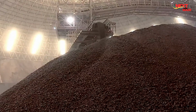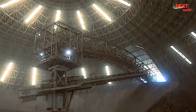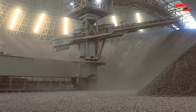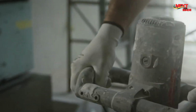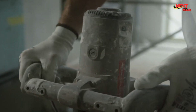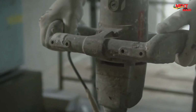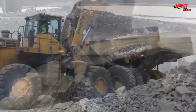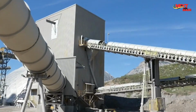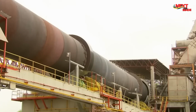The cooled clinker is then ground with gypsum and other additives such as fly ash, slag, or pozzolana in cement mills to produce a fine powder. Gypsum is added to control the setting time of the cement. Once prepared, the cement is ready for transport to the concrete factory. Because cement is such a crucial part of concrete, cement plant laboratories check each step in the manufacture by frequent chemical and physical tests. The labs also analyze and test the finished product to ensure that it complies with all industry specifications.